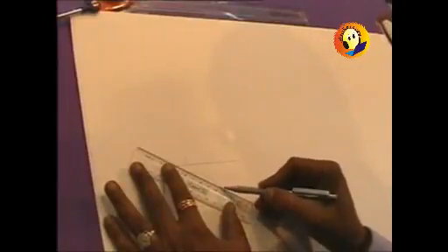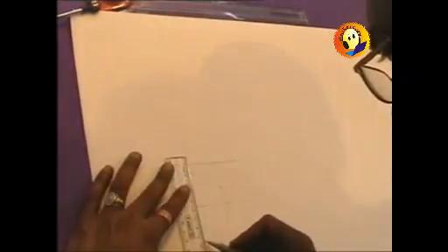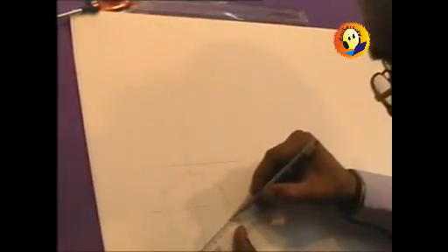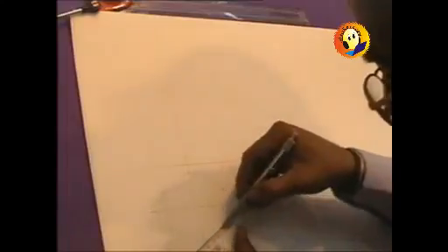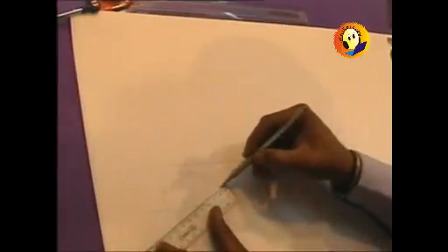So we will first of all draw the hexagon with two sides perpendicular to XY, one of which is going to work as the line of rotation. As we are drawing the hexagon itself using the circle technique, it will not be difficult to join all the corners to the vertex, because obviously the center of the circle will represent the vertex. So I am just drawing the hexagon and showing all the generators. Initially the center line that I had drawn will now be overwritten by the generator of that particular pyramid.